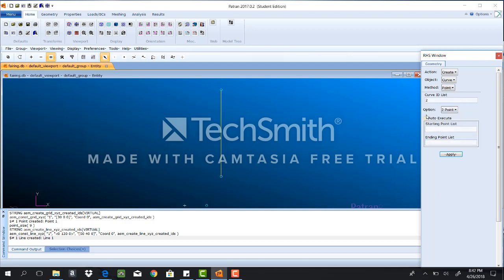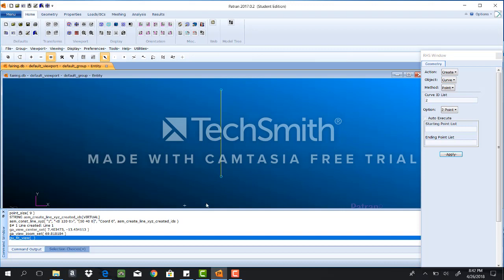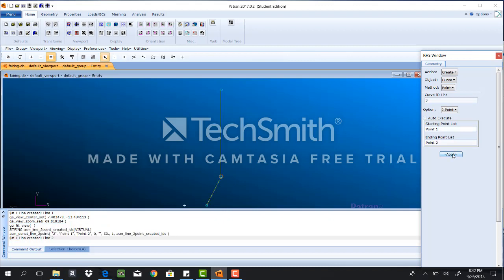Then we're going to create a curve method point. We're going to select the point 1 on the starting point, and in the ending point list the point 2, which is below, and then click apply.